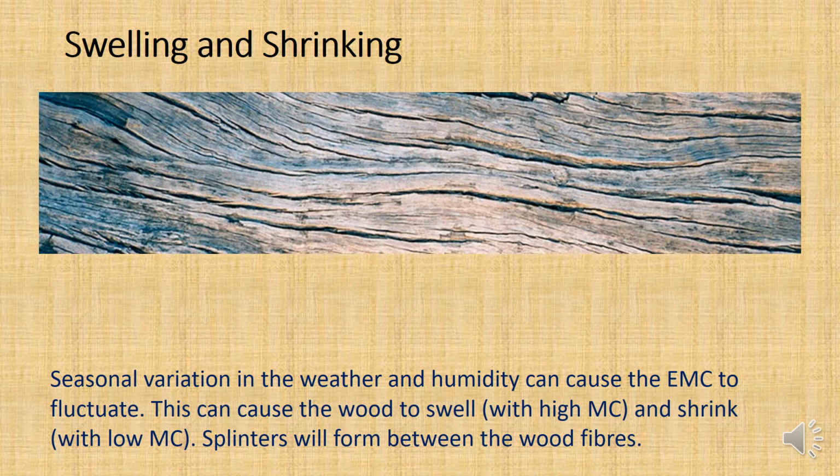and that's going to lead to this swelling and shrinking. And so that's why it's very important to have treated timber that can stop this, or if wood is exposed to the environment where it's always wet and then dry and wet and then dry, you paint it so moisture cannot actually get into the wood. You give it a waterproof barrier by painting it. So this wood here was not painted, and you can see that there's been a lot of damage to it from the swelling and the shrinking.